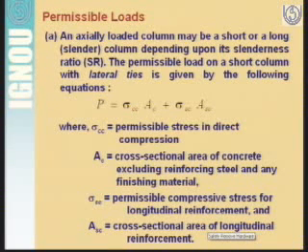because based on that we have classified the columns as short and long. The permissible load on a short column with lateral ties is given by the code as, you can see this formula, P equal to sigma cc into AC plus sigma SC into ASC. This is defined in code. You can find this in IS 456, and this is the formula for the working stress method. You can find the formula for the limit state method also in your code.